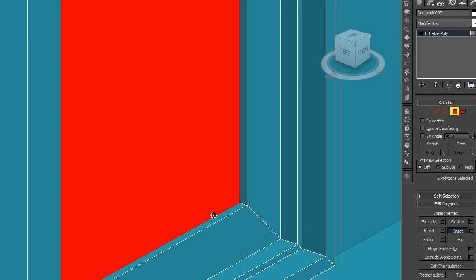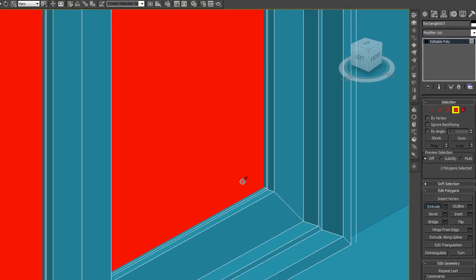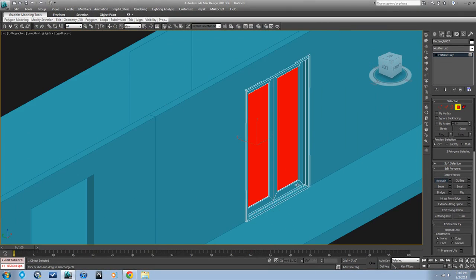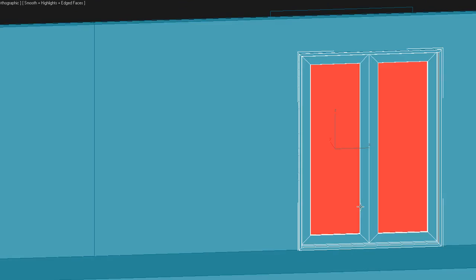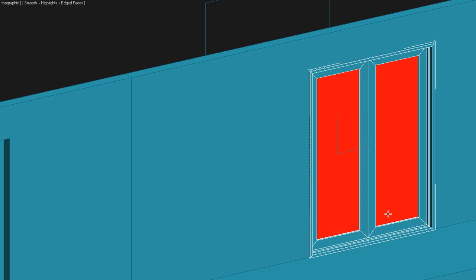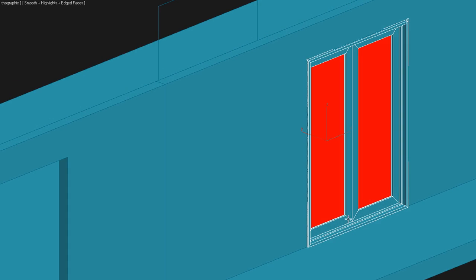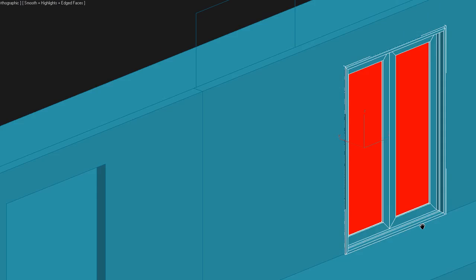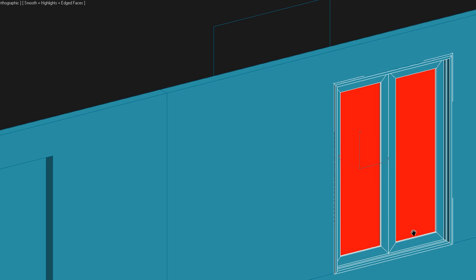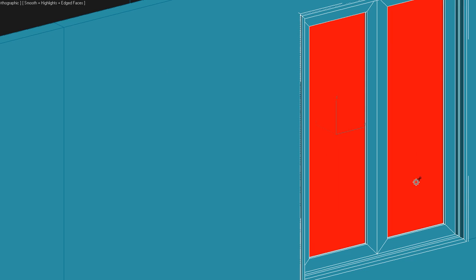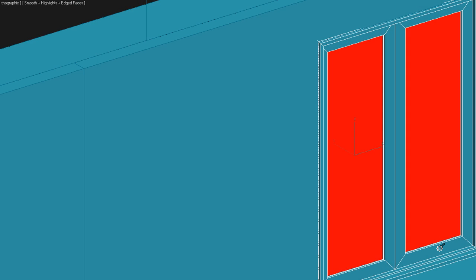And if you want to add a little more detail, we're extruding back for the glass now. So this last plane will be our plate of glass. The highlighted one right now is our plate of glass for that door. So you can see we got some nice little doors there, just by insetting, extruding, insetting, extruding, insetting, extruding, splitting, insetting, extruding. Those kind of poly tools. There's just no faster way to do that. If you're doing it all with splines, it would kind of take you forever, and you could do sweeps and all those kind of things. But this adds nice dimension to that door just really quickly.